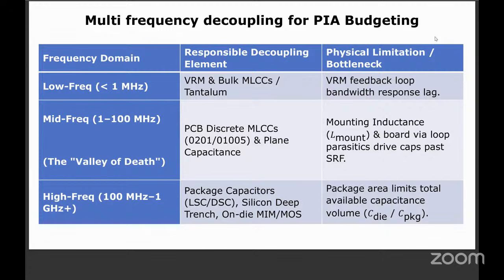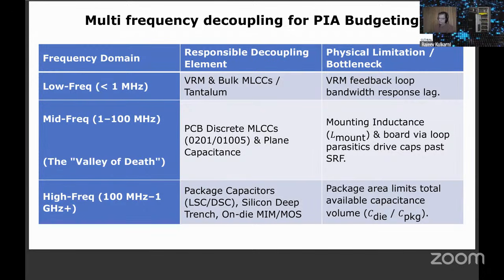Then that is the valley of death. What is the valley of death? I will tell you. I'll show the image. High frequency, 100 megahertz to 1 gigahertz, will be generally within the package. The capacitors will be within the package.